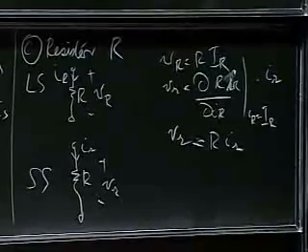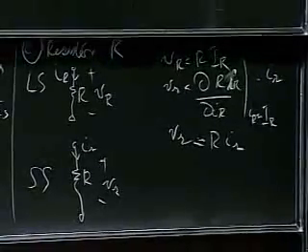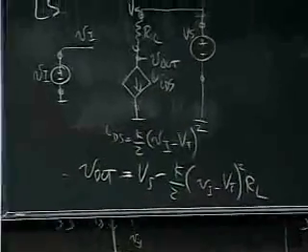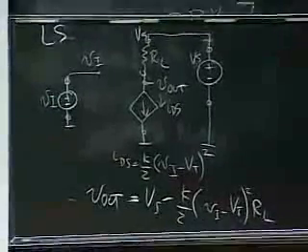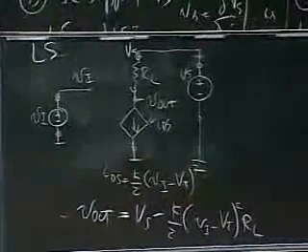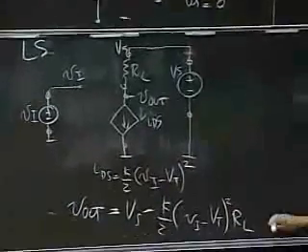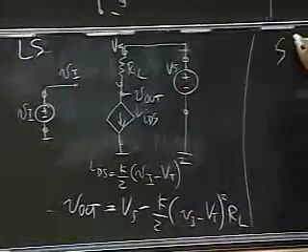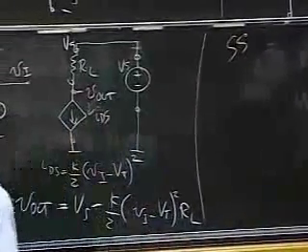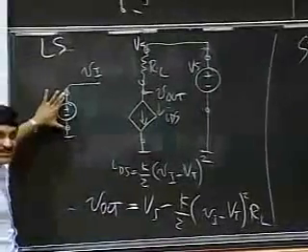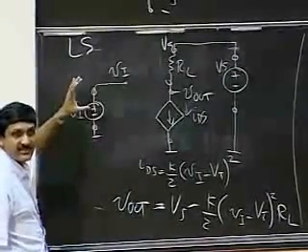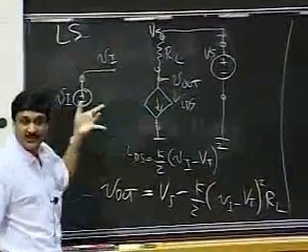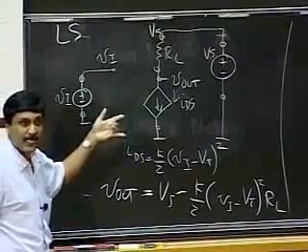So as a final step, on page 8, I'd like to very quickly draw for you the small signal circuit and then analyze it. So this is the large signal circuit. And let me draw the small signal circuit. The method says simply pluck out each of these elements, and replace each of these nasty nonlinear elements with the corresponding small signal linear equivalents.